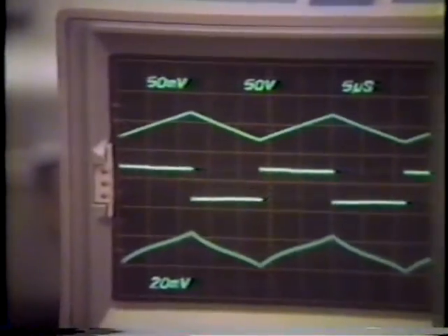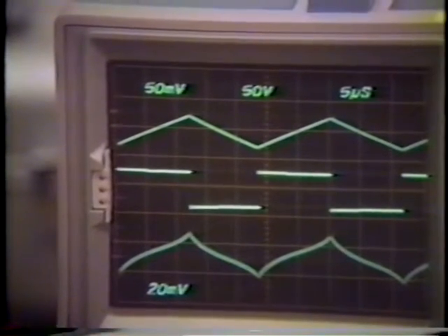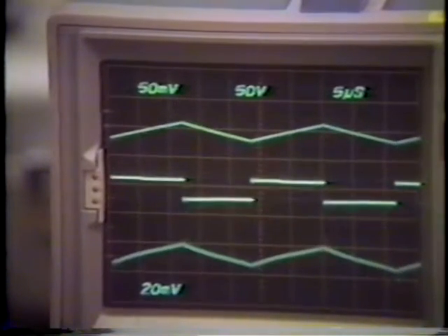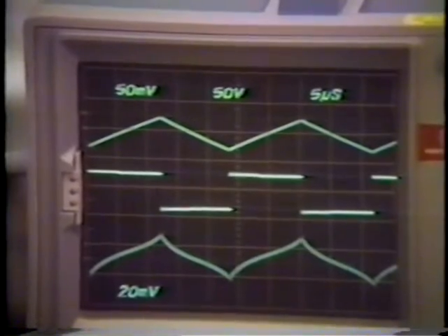Now let us show again, if we go back to our original 40 kilohertz switching frequency, and if we now start driving the core with the voltage source, increasing the voltage, we again can get into saturation, as we see by this spiky behavior.